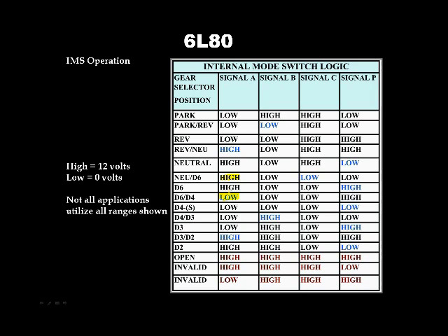When we see a particular switch change positions, we know that the guy's making a transition from one gear range to another. That gives us the ability to anticipate the engagement. So my point is, you'll see some stuff in between the gear ranges, and pretty well every manufacturer does this. If we move from reverse to the position between reverse and neutral, you're going to see a switch toggle as we're making the transition into the neutral range.